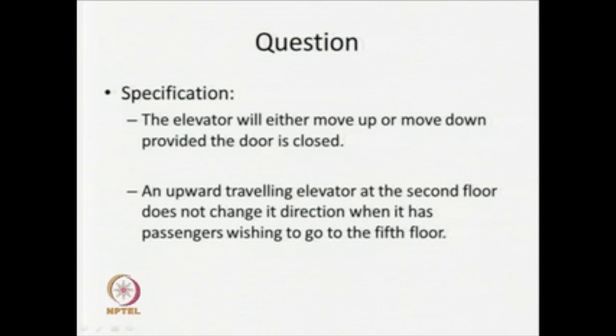So, this is basically the algorithm that we have incorporated in our lift controller, because we should have some protocol to give the service to the passengers. Generally, in a simple algorithm or simple notion, if the lift is moving upwards, then what will happen? Generally, it is going to service the requests for all upward direction. Why? Because as a designer, we know that if some lift is moving up and from some floor we are going to come down, then there will be a change of direction in the motor.